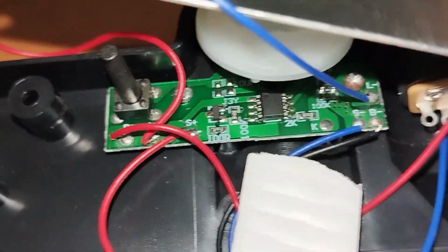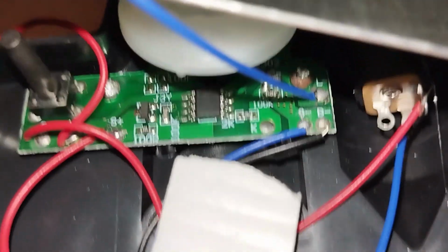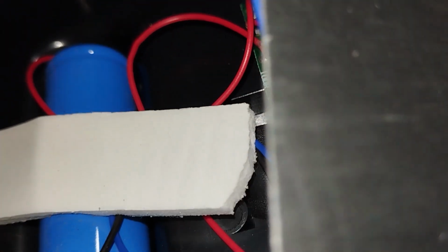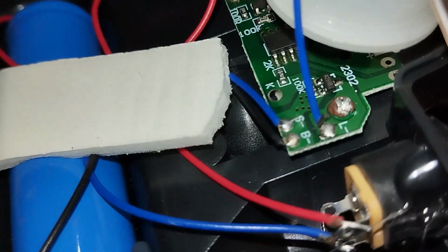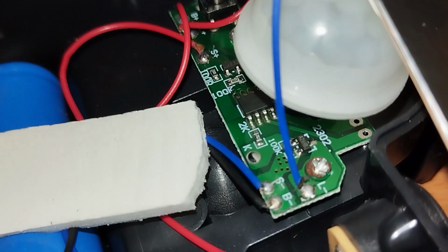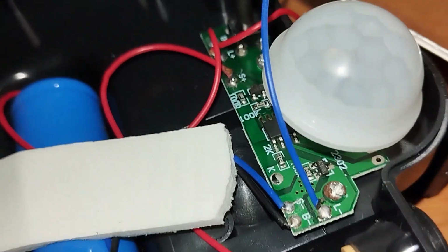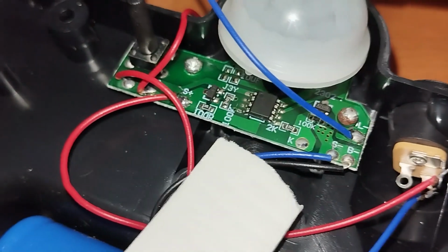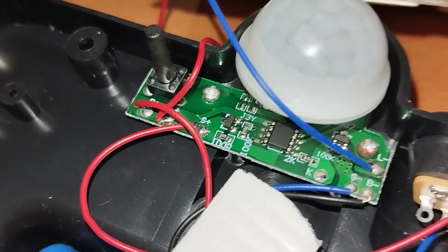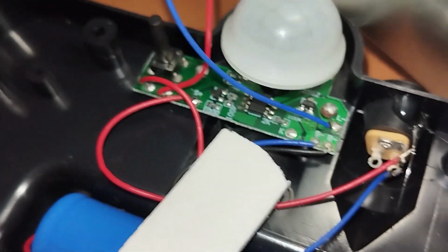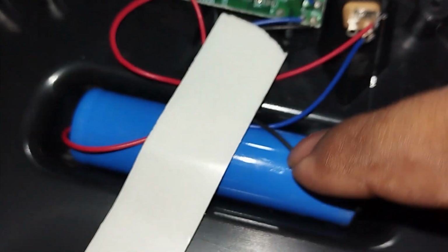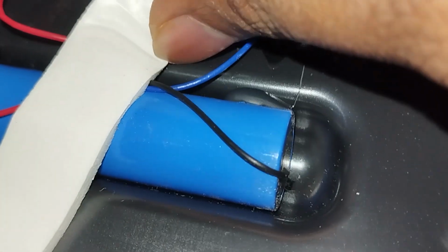Then the battery and the BMS, we have to deal with the BMS. I hope the BMS has short circuit protection, over voltage protection, over discharge protection, overcharge protection, and overload protection, and if you have multiple cells, cell balancing. And then the critical circuitry, you have to monitor the battery temperatures. I'll leave as much footage as possible for you. That is a typical board with some sort of DIY soldering, because Chinese products don't want to invest a lot of time in the installation, because they need to save time and produce many more units.